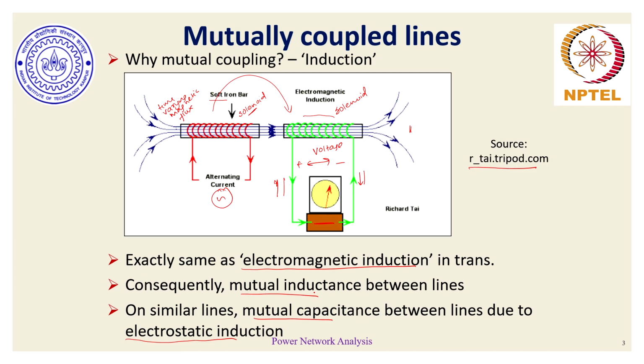Mutual coupling often gets strengthened for high operating voltages, usually more than under low operating voltages. So typically for distribution lines, the coupling effect is a little lesser, although in distribution lines the lines are placed nearby, whereas in transmission lines with transmission towers having high right-of-ways, the higher operating voltage effect gets minimized or diminished because of large spacing. So the corresponding coupling effect in transmission lines compared to distribution lines is more or less comparable or similar.